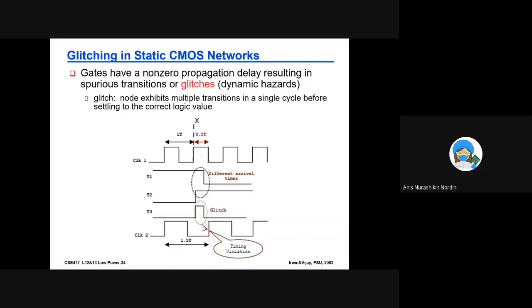And you put this clock into different gates, right? So let's say you are ANDing or NANDing these signals. As you can see here, when you multiply this by this, you will get this glitch. This signal is supposed to actually end here, right? So when you have this, if it is 0 times 1, it should be a 0.